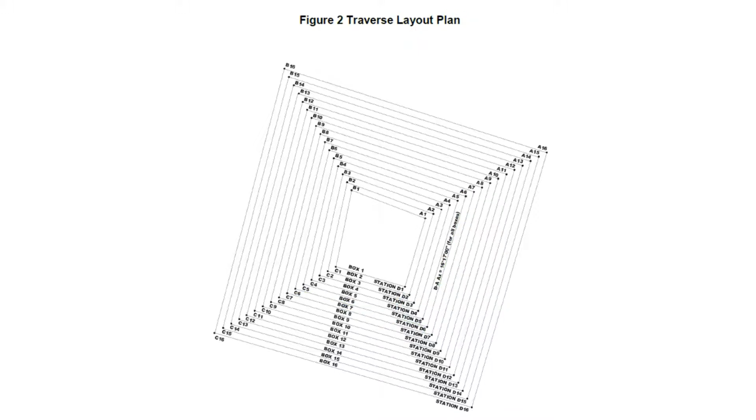The next step is that we'll move our total station over to station A and set up prisms on station B and D. We'll repeat the process of zero setting our angle on station D and taking a distance measurement, and then rotating our total station towards station B, reading the horizontal rotation and taking another distance measurement.